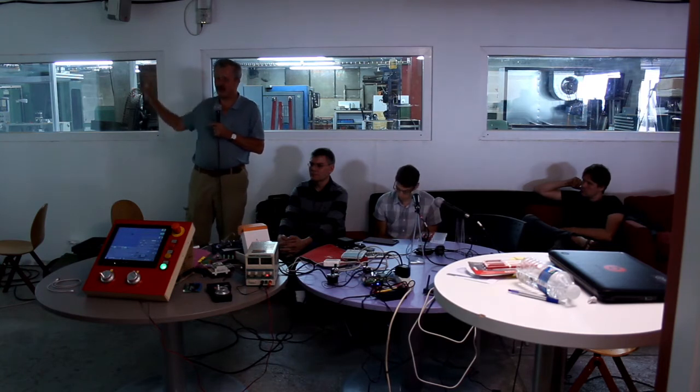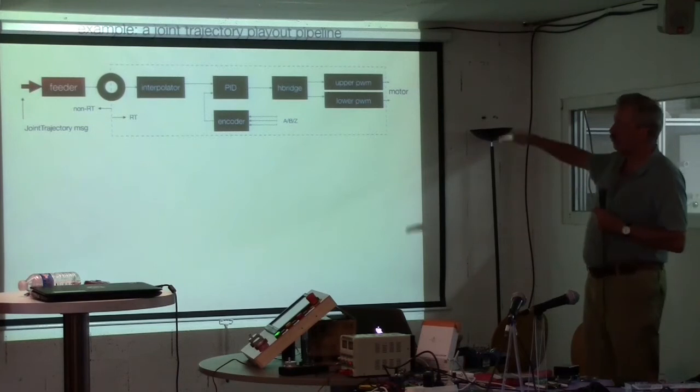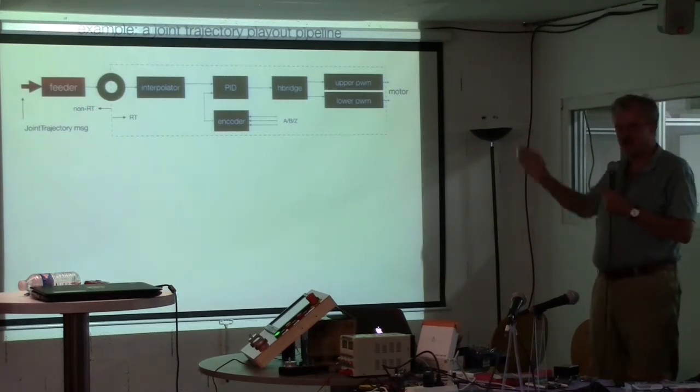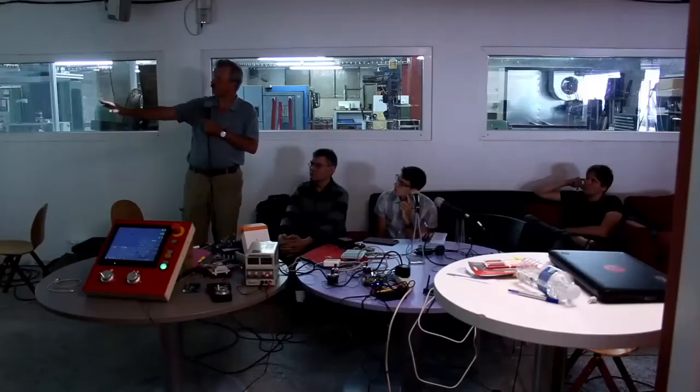So the playout pipeline takes such a segmented curve and translates it into electrical signals to drive a particular joint. Now, for a given machine, like a 3-axis mill, you would have 3 instances of that whole pipeline for the X, Y, and Z joints, of course. And the driving layer generates all 3 axes, or joints in that case, because it's a trivial kinematics machine, in parallel. So the first step you do is you have to interpolate these segments over time for a given point in time.